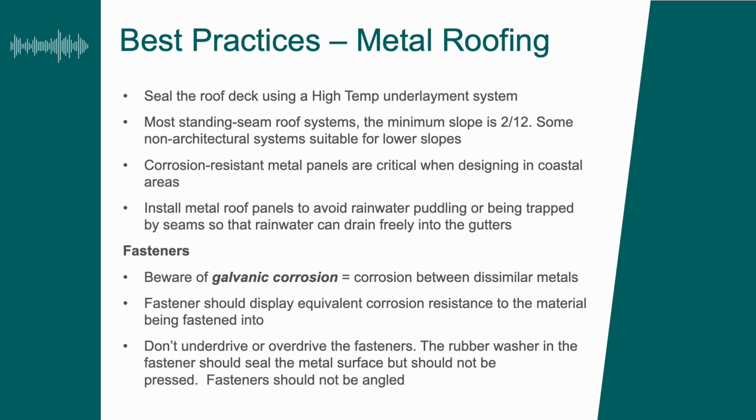And don't underdrive or overdrive the fasteners. With metal panel systems where you're using a rubber washer, if you overdrive it, it might break that washer, so you have to be careful of doing that. And fasteners should not be driven at an angle.